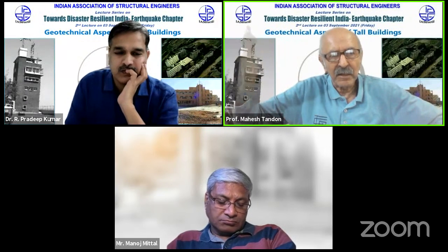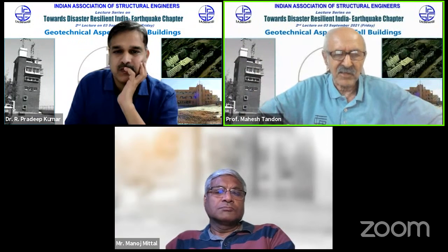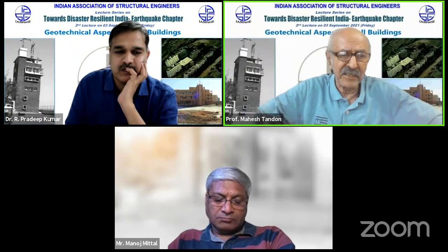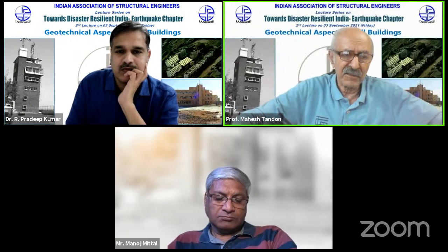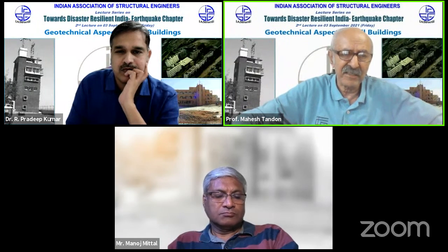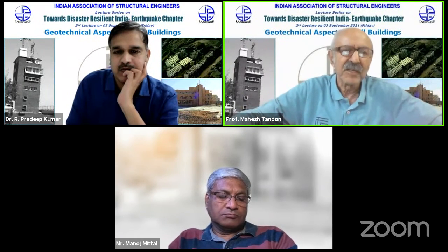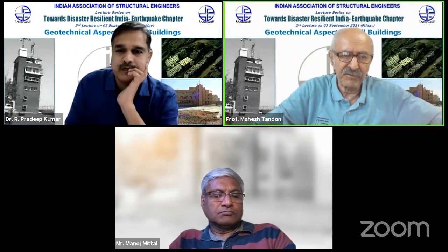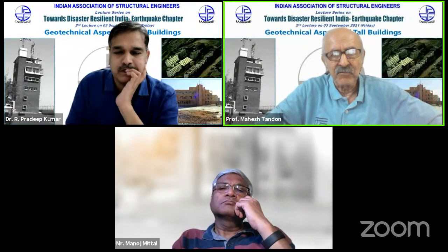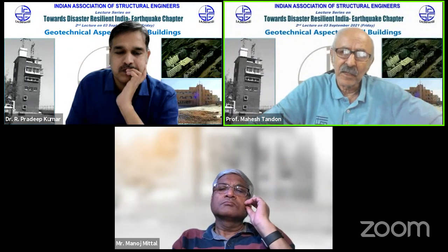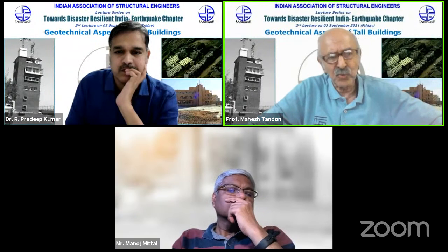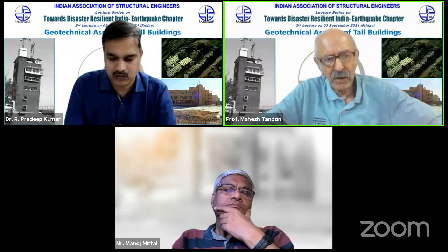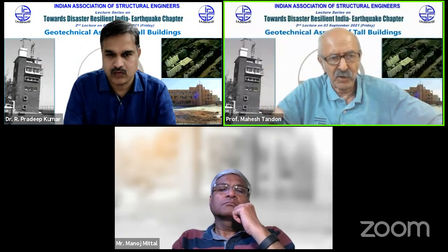But for simplicity in all structural engineering applications, we try to use a bilinear spring so that it is easy to understand and you can finish the problem quickly. How to do this is given in a number of books, but we are also going to have a publication soon in the Indian Roads Congress, where we will explain how to idealize it, depending on the type of soil.